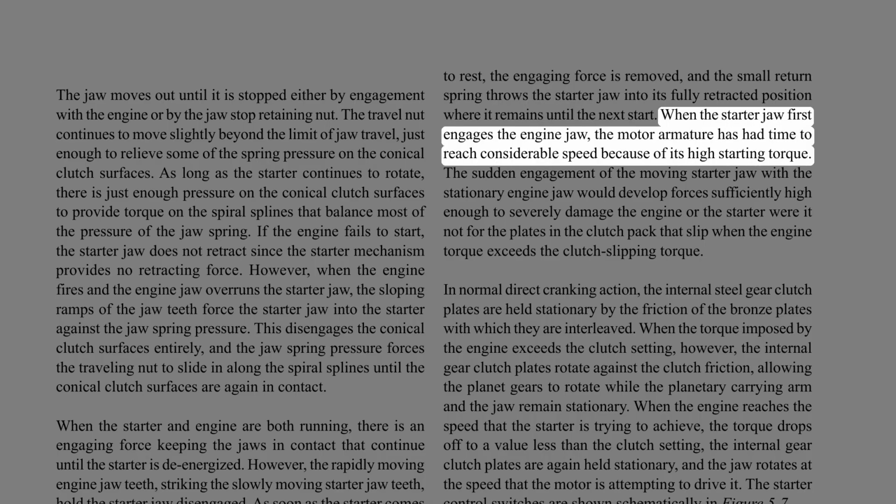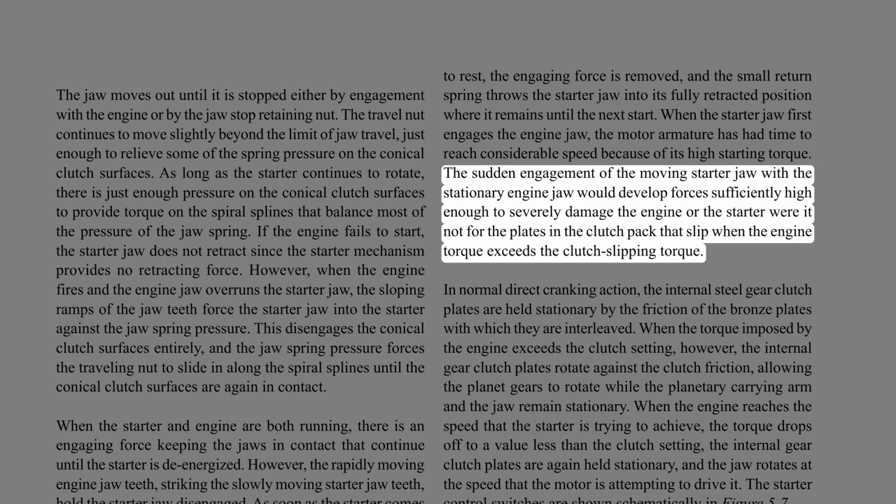When the starter jaw first engages the engine jaw, the motor armature has had time to reach considerable speed because of its high starting torque. The sudden engagement of the moving starter jaw with the stationary engine jaw would develop forces high enough to severely damage the engine or the starter, were it not for the plates in the clutch pack that slip when the engine torque exceeds the clutch slipping torque.